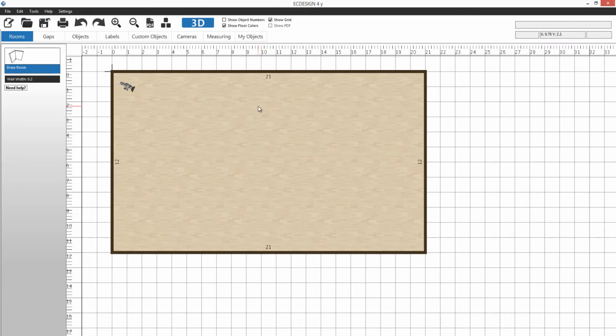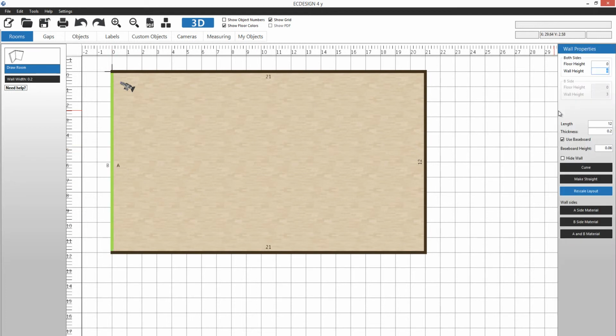But now since I have a sloping ceiling, or I want the sloping ceiling from here going down to here, that would provide me with a problem because if I started splitting this room, that sloping section would actually stop where I make my wall section right here. So what I need to do is first select and create a sloping ceiling. I actually did that. It's 6 meters over there and 3 meters on this side, as you can see right there. So we have the sloping part now. But if I split this, that would end the sloping section where I do the split, where I create that wall section. But like I said, I wanted to have a special floor over here.